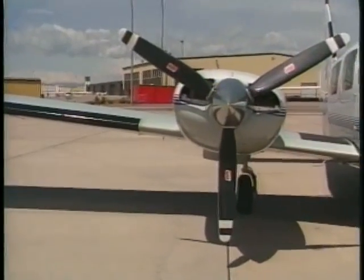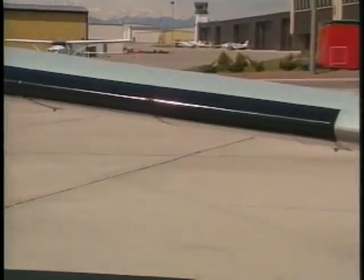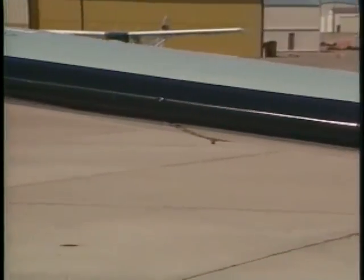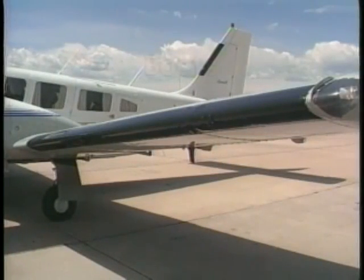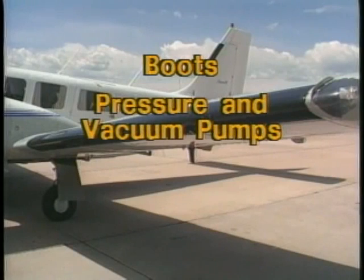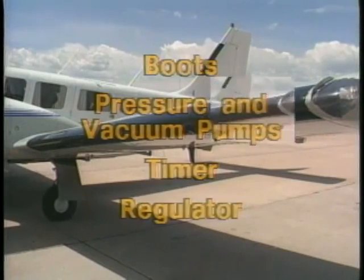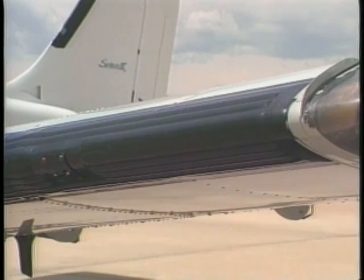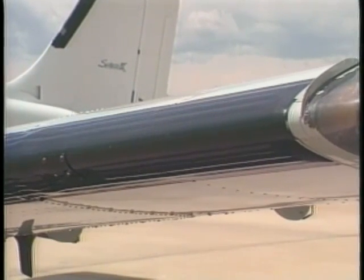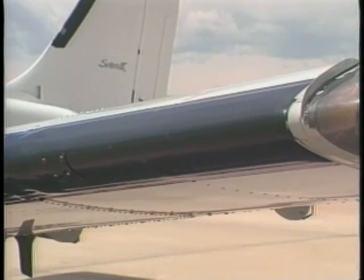Many piston-powered aircraft have pneumatic airframe de-icing systems on the leading edges of wings and tail surfaces. Normally, this system consists of inflatable boots, engine-driven pressure and vacuum pumps, a timer, and pneumatic regulators. The engine-driven pressure pump inflates the boots while the vacuum pump deflates the boots and supplies enough suction to keep the boots flat against the leading edge of the wing.